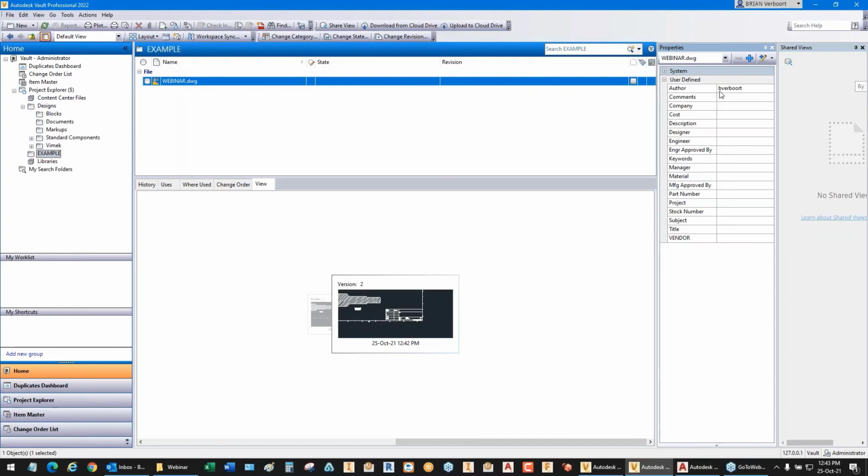Look what's happening here in this properties panel in Vault Professional. You can see that we have several properties. Those are the other properties that kind of went along for the ride as I blocked up that title block. But now look, we've got a vendor property here that wasn't there before. This is here only because we did the work on the front end. We provisioned it both in the ADMS console and in the Vault client in order to get access to this.